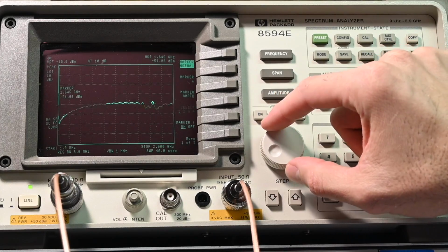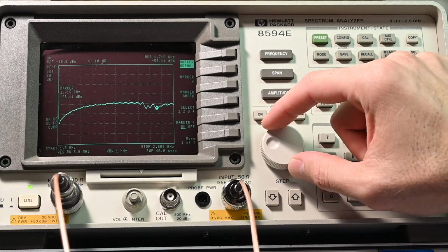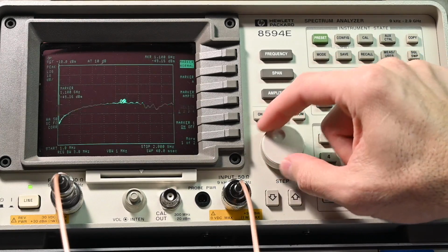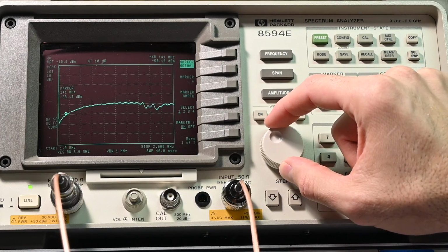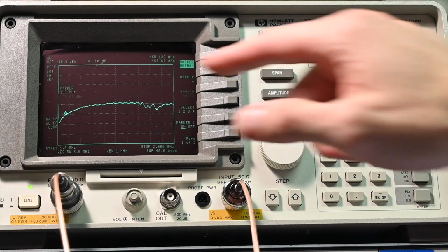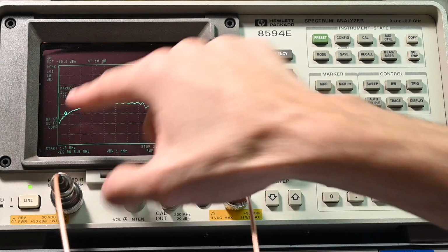Was that about minus 50 dBm, and then it drops down there to minus 55, 56 or so. But yeah, this definitely fits with the response that the spectrum analyzer was indicating earlier in the video, where we were seeing a huge drop in the amplitude, and look at how it rolls off.